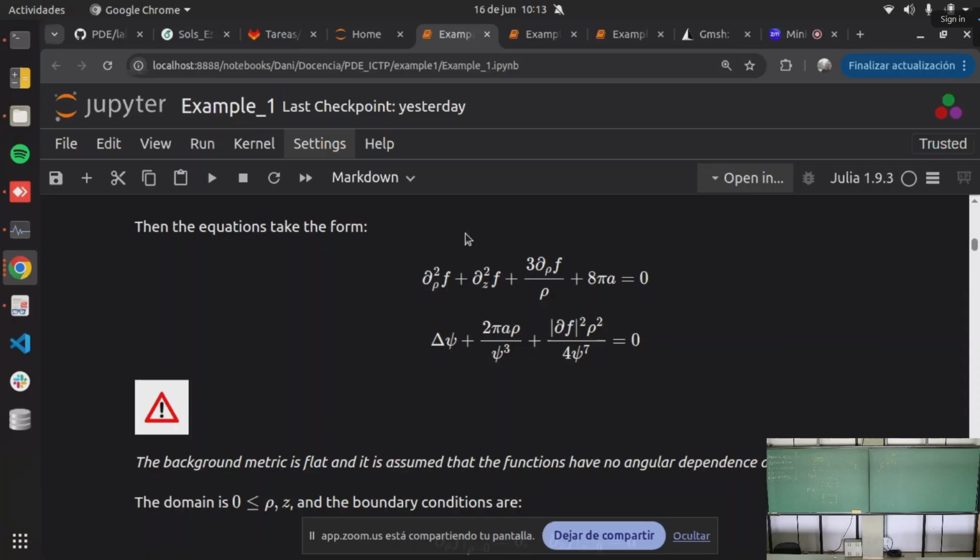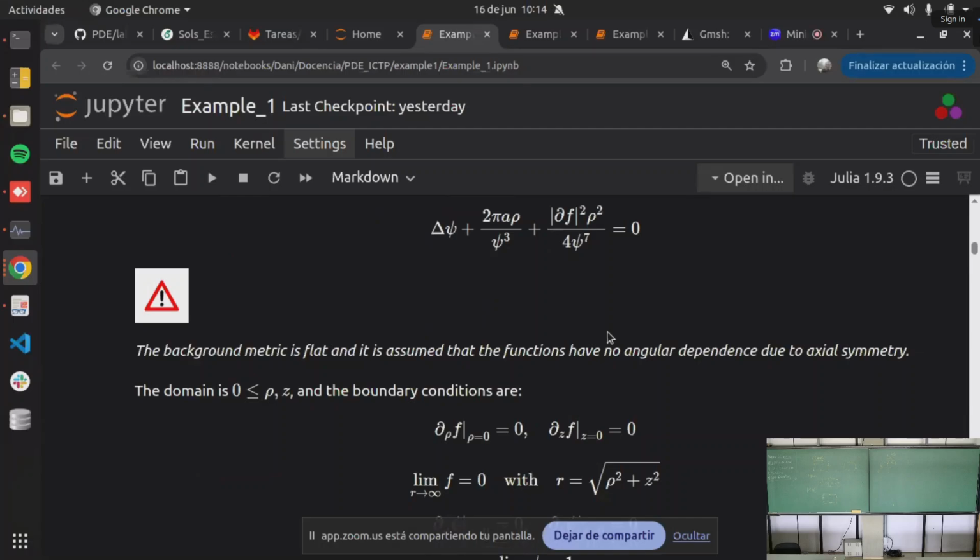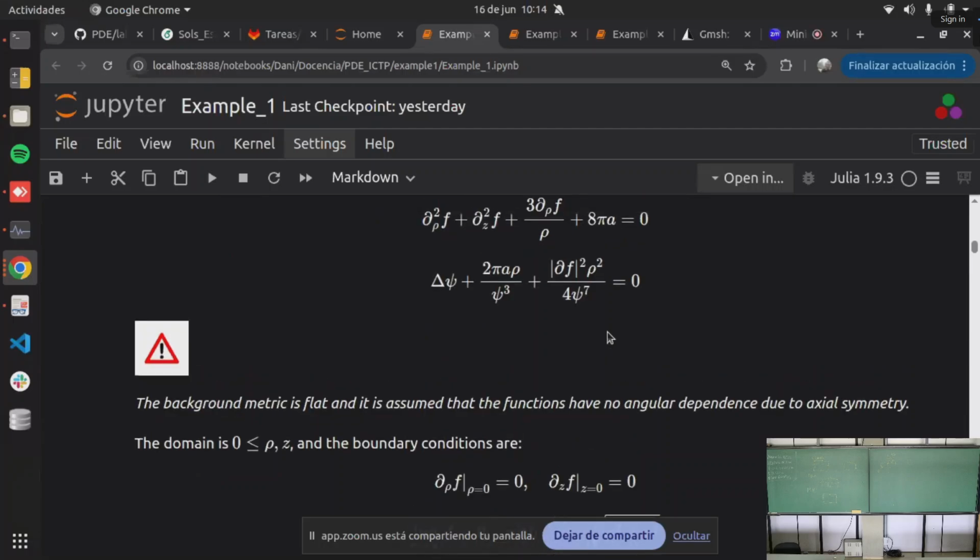We have to note that this is a nonlinear PDE, and in this case, the equation has a weak coupling. Note that we can solve first the equation for F, and after that, having the solution for F, we can use it to find the solution for C. This is an elliptic PDE, so we can use finite elements to solve it. We will do it with Gridap.